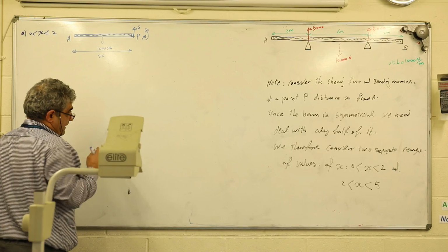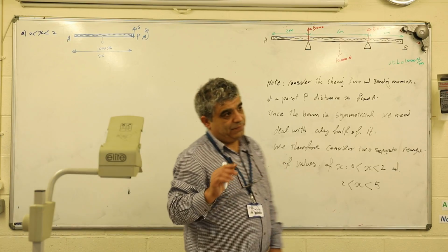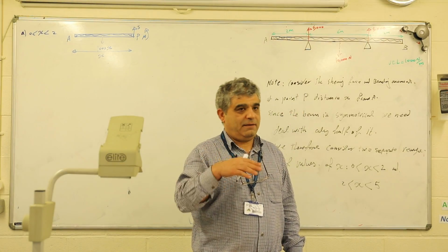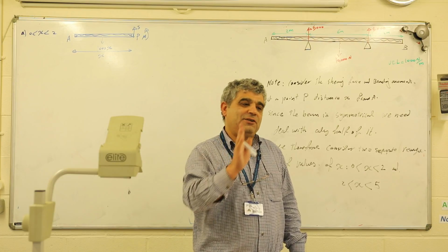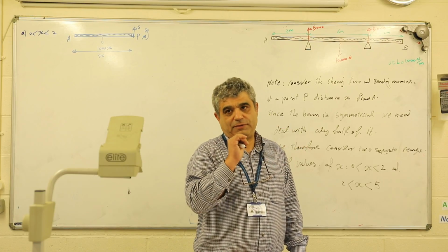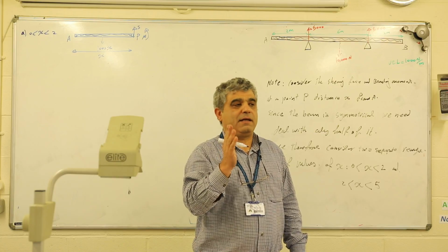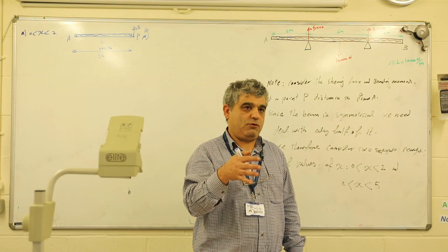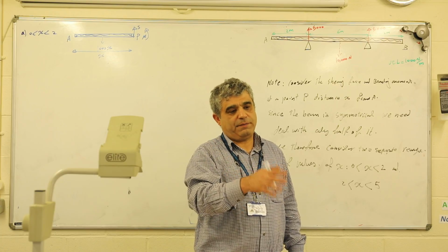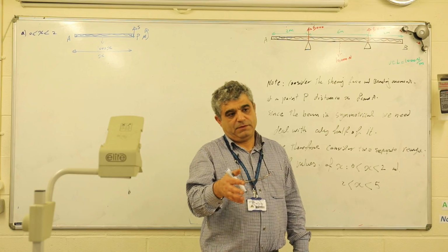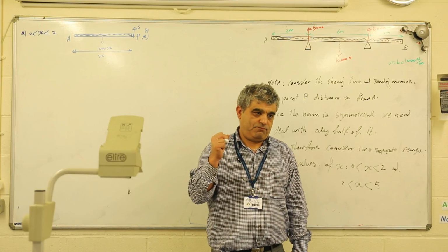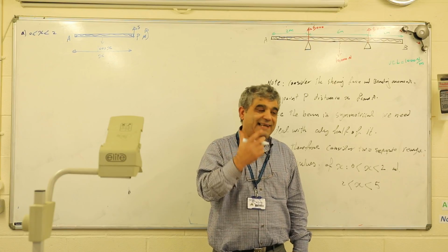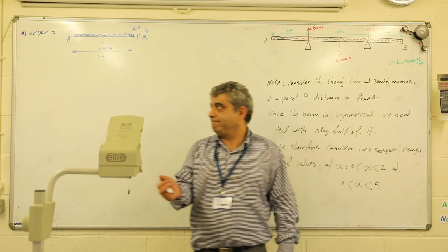The first thing you do is do it for half of the beam, and then you can draw the bending moment identical to the other side. I show you how to do that. And then cut the beam. Draw the shear force and bending moment. Construct the equation of the bending moment and shear force when you cut the beam for the required distance.